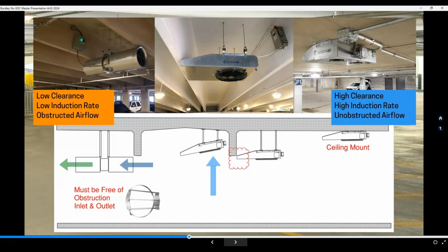So as an example, in this complicated structure here, the only portion of the centrifugal jet fan that needs to be fully beneath structure, even as close as we are in this application, is just the discharge of the fan. For perspective, I want to point out to you the discharge of that fan is 3 inches. It's actually 2 7/8, but we call it 3 inches. So you have much greater ability and design varieties at your disposal rather than being limited to the challenges provided by the larger size of the axial jet fan. And as illustrated by the jet fan on the right, they can be installed tight to the ceiling.